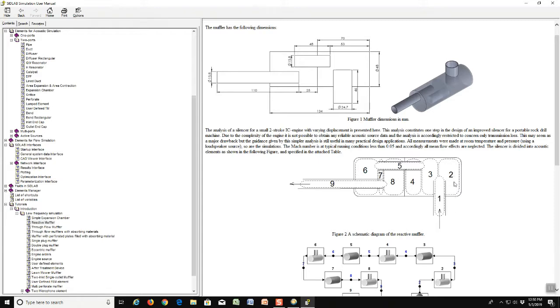Now, where is the side pipe? There is none, but the length of this side pipe is actually, in this case, the distance from the inlet pipe to the end of the chamber. And when you do a SIDLAB model, you have to pick a direction. So actually, this is the direction back and forth. But because there is a wave that goes from the inlet and is reflected back this way, this volume acts like a quarter wave resonator.